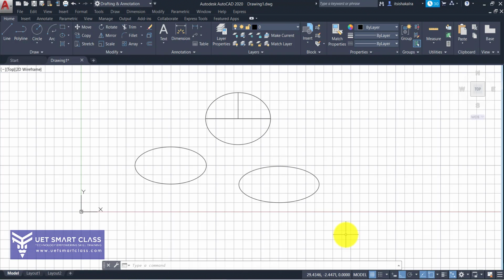Okay. Now remember one thing, the higher the value from 0 through 89.4 degree, 89.4 degree, I repeat, the greater the ratio of minor to major. Like I said, the saucer plate. As and when you rotate, it becomes an ellipse. But when you see it in the 0 degree, in front of your eyes, you will see a thin line. Okay. So 89.4, why? Because from 89.4 to 90.6 degree, the values are invalid, because the ellipse would always appear as a straight line.